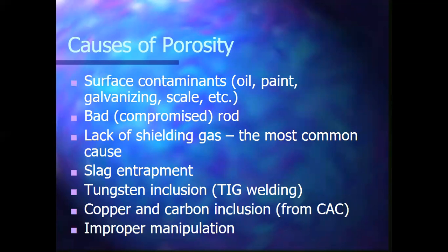You guys forget to turn on your bottle. You guys come up and you say, Mr. Scott, what's wrong with this weld? And like I said, I can hear he doesn't have his gas bottle on. Sounds like ripping a wet cotton t-shirt versus that nice, hard, sharp electrical kind of crackle it should have. That one's one of the most common. Then you got a dirty tip. You're not getting the gas to the weld properly. Slag entrapment, you get junk in your weld, probably by bad manipulation of your gun and your electrode.